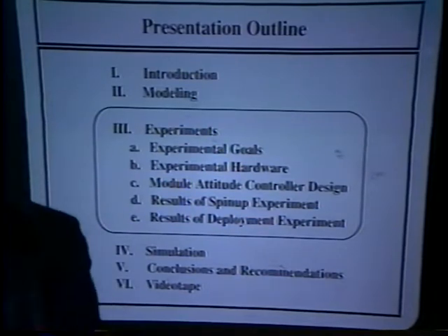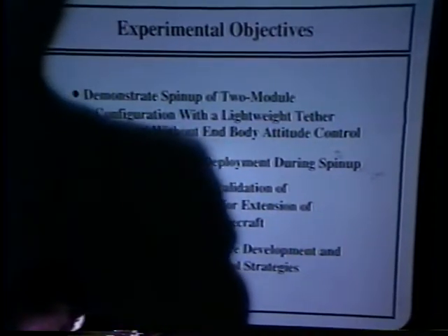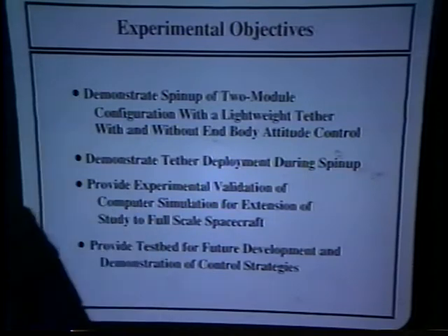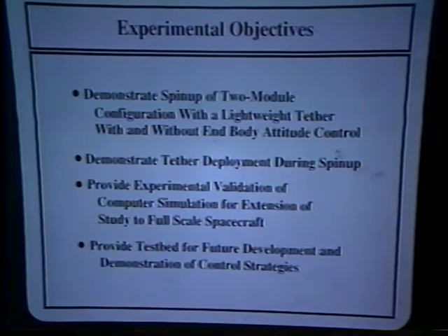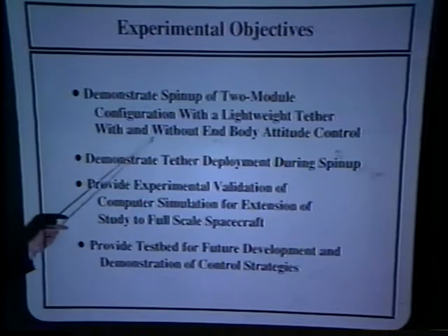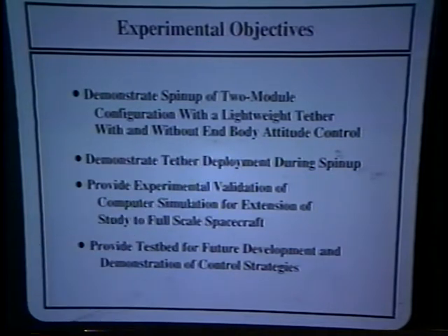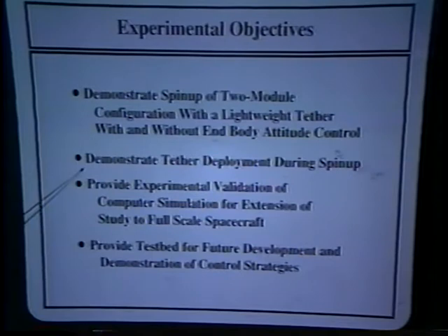First of all, the objectives of the experiment were to demonstrate spin-up of a two-module configuration with a tether of negligible mass with and without active in-body attitude control. Next, to demonstrate deployment of the tether during spin-up. Also to provide an experimental validation of the computer simulation that I wrote so that the study that we've done can be extended to a large spacecraft with a non-negligible tether mass. And finally, to provide a test bed for future development of control strategies for such a spacecraft.